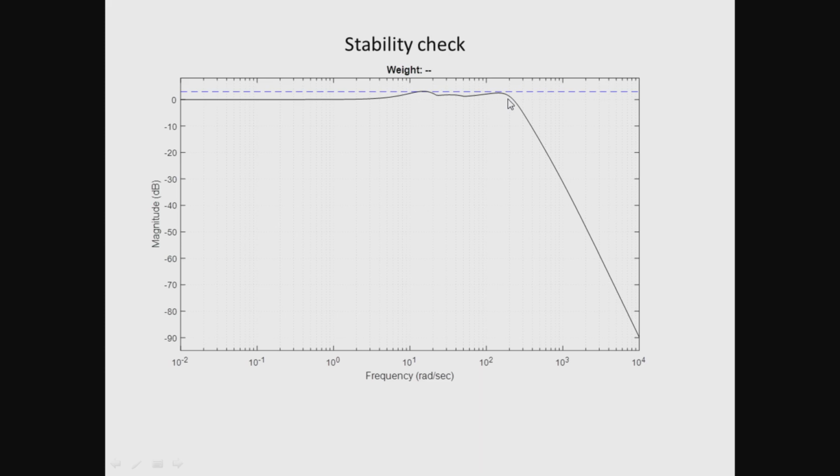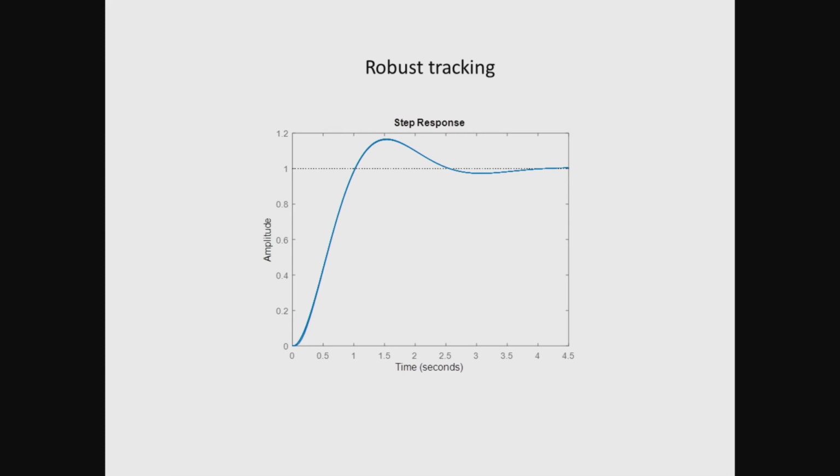So, having therefore completed the different steps in the design, performed essentially loop shaping to determine the structure of the feedback controller and then design the pre-filter, and also verified the closed loop transmission function T1 satisfies the specified stability limit, the last step is to verify that the disturbance rejection and robust tracking specifications have been met in the time domain. So, what I have done therefore in the next slide is plotted the step response of the closed loop